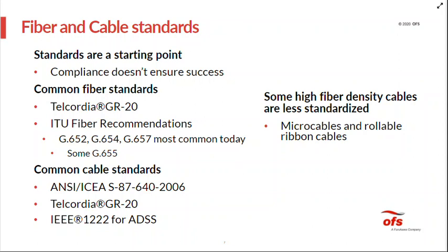Some common cable standards are the ANSI ICEA standards, as well as Telcordia GR-20. And then for those people who are deploying all dielectric self-supporting cables, the IEEE has a different standard, and that's IEEE 1222, which is a standard predominantly focused on ADSS cables. There are a few additional types of cables out there that are a little bit less common. But with what you saw on the last slide, as well as these standards, this covers probably 80 to 90% of what we see in the outside plant today.